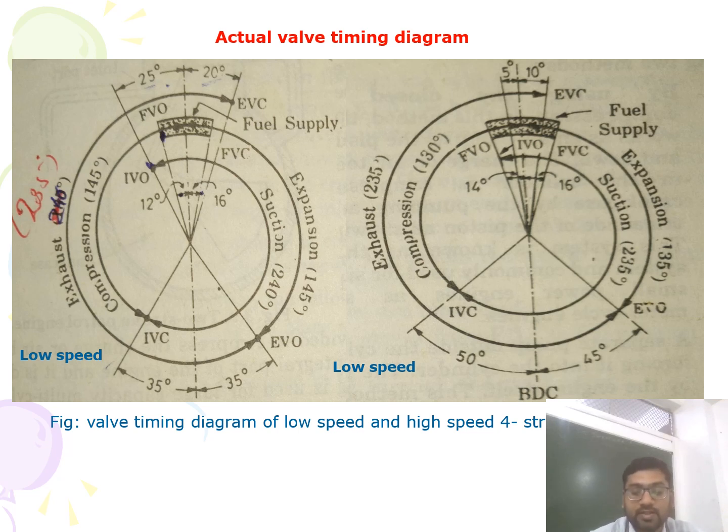In the diesel engine, the valve overlap provided is sufficiently large, 45 degrees, compared with the petrol engine, which has about 13 degrees. More overlap is not possible in the petrol engine because the mixture of air and fuel would pass out with the exhaust gases, meaning the charge will be diluted, which is highly uneconomical. This problem does not arise in the diesel engine, because only air enters during the suction stroke. The valve timing of the engine has to be adjusted depending upon its speed.